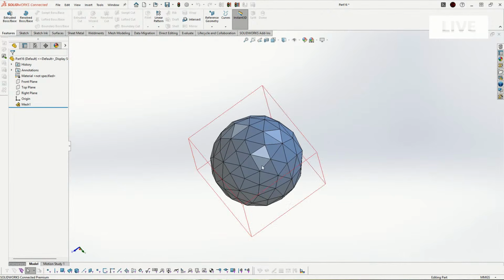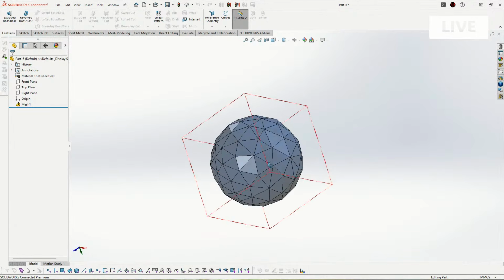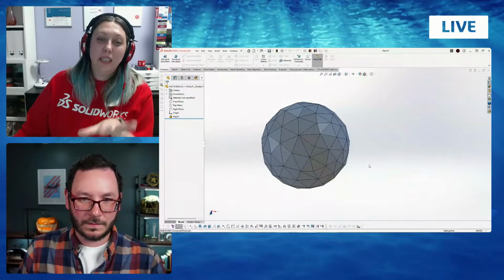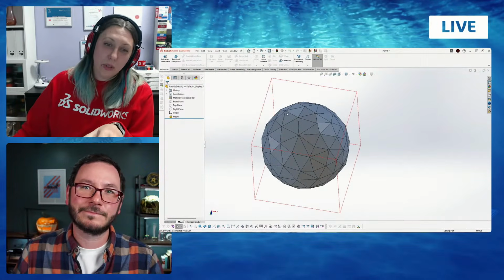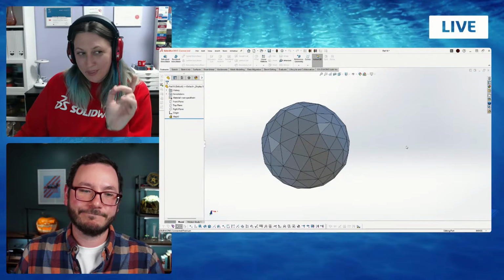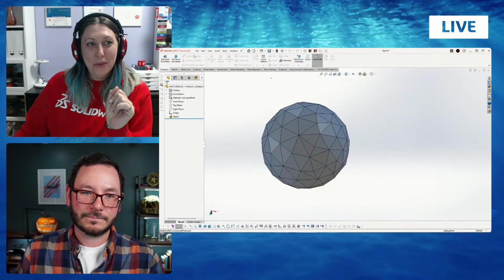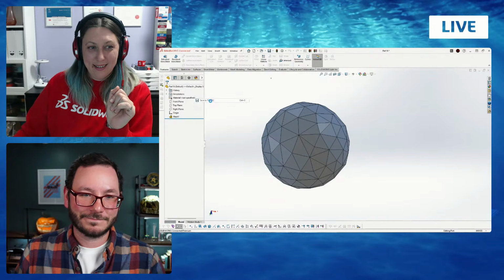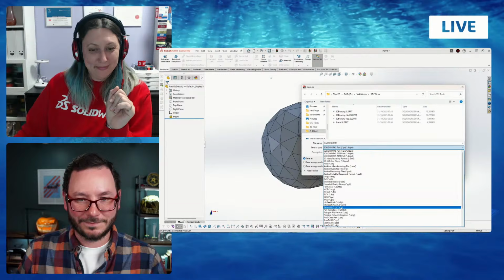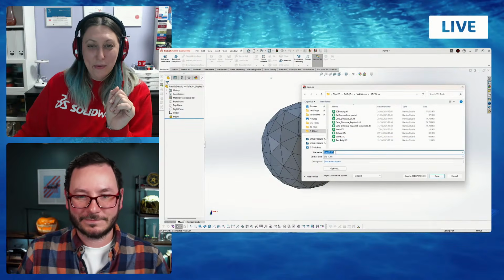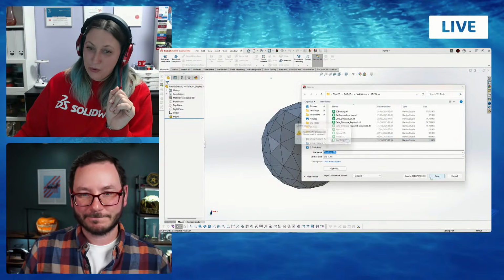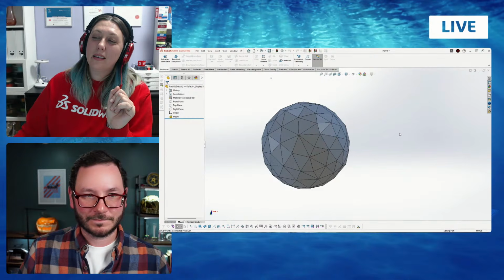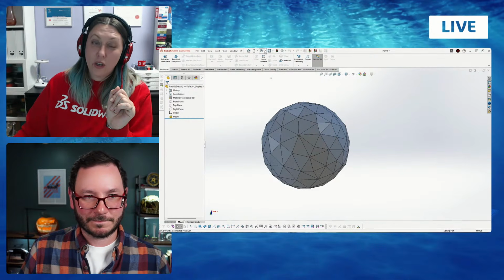That's it. Once this is done, however, the easiest way won't be to convert face by face. Now you would like to save this as STL again. And then you would want to import this as an object.